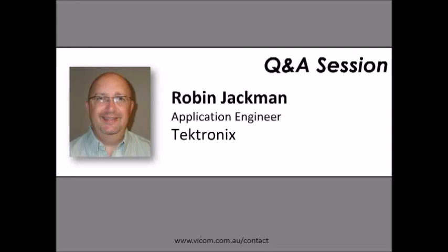Wow, okay. That's impressive. Our next question is, are Tektronix MDOs immune to compression effects from different frequencies? No. There are compression effects in almost all instruments. The Tektronix MDO 4000 is what I call an entry-level to mid-level spectrum analyzer. It has a different design than a swept-tuned or a real-time signal analyzer.